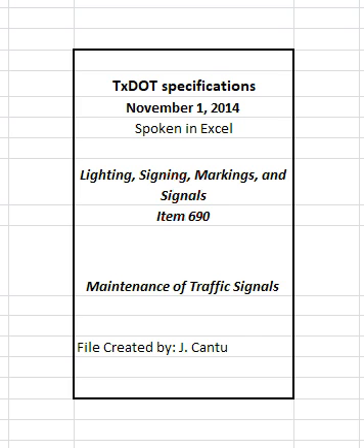4.15 Cables. Install, repair, replace, remove, or modify signal, loop lead-in, electrical, communication, or illumination cables in conduits or along messenger cables in accordance with item 620, electrical conductors, in accordance with item 684, traffic signal cables, as shown on the plans, or as directed. Attach aerial cable at 1 foot intervals using approved cable ties along a messenger span cable. Install a drip loop with at least 2 turns at each pole, signal head, and weather head.